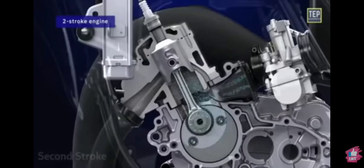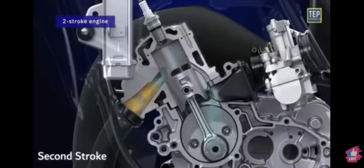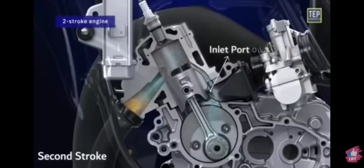In the second stroke, the compressed charge is ignited in the combustion chamber by means of an electric spark produced by the spark plug, slightly before the completion of the compression stroke. Due to combustion, the piston is moved downward. During this stroke, the inlet port is covered by the piston and the fresh charge is compressed in the crankcase.